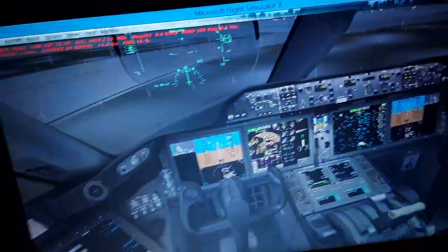We have the runway length, the runway slope, the wind direction and speed, the barometric pressure of the outside air, the density of the air and the temperature of the air, and also the runway conditions, whether it is icy, dry or wet. We're going to have all the calculations for the takeoff speeds. Using the flight management computer, this gives us V1, V-rotate, and V2, which is the takeoff climb speed, and we're going to have V2 plus 15. It's going to be our flight speed after takeoff.